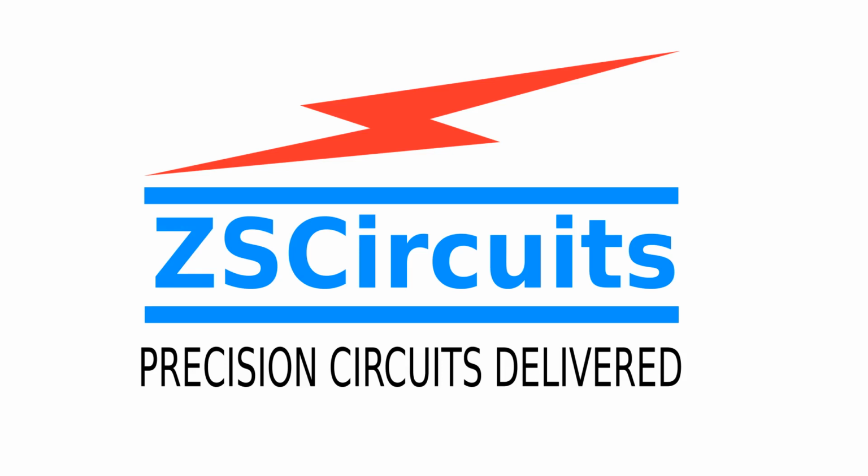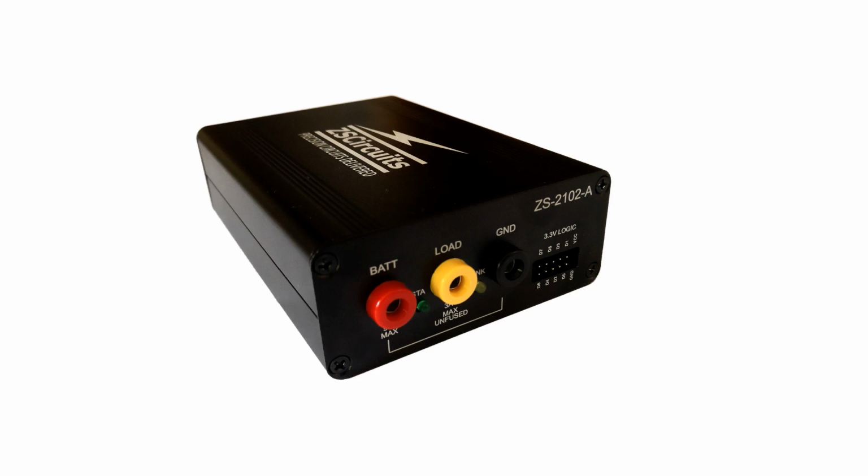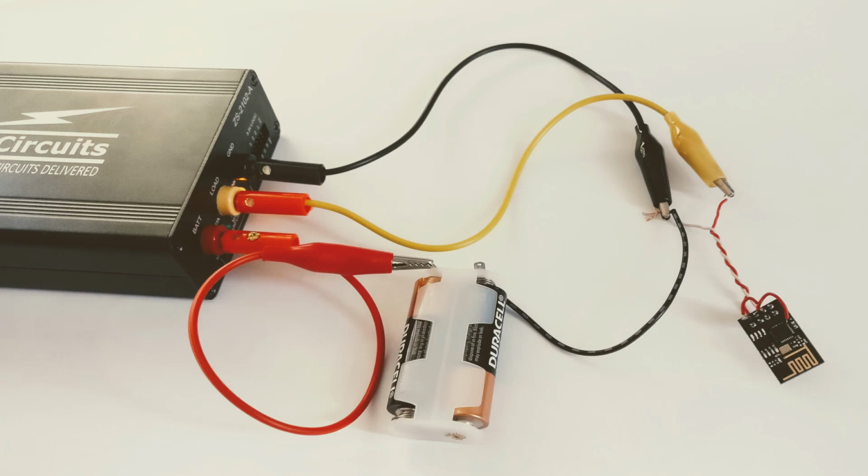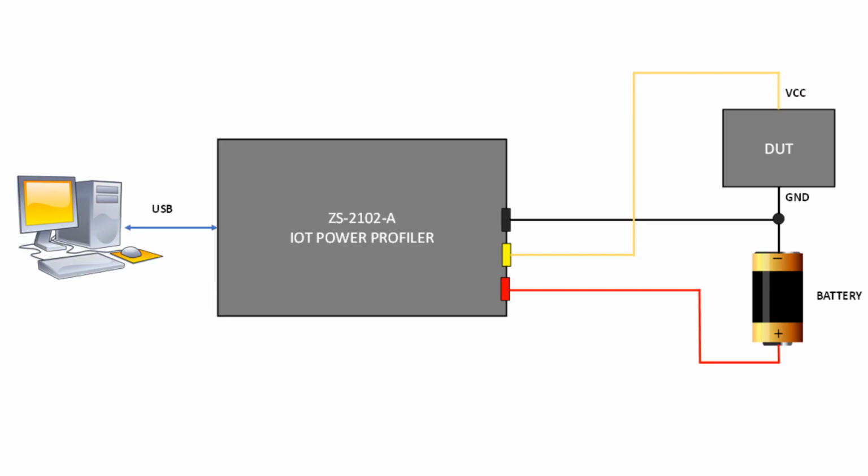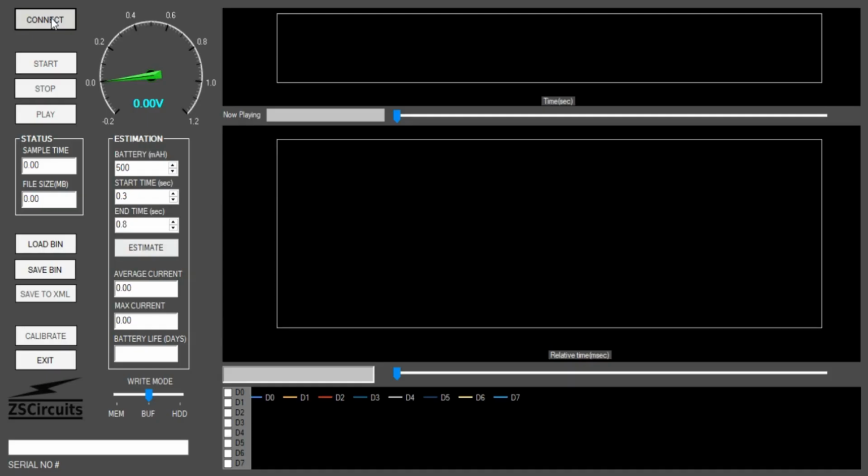This is a demonstration of the capabilities of the IoT Power Profiler tool, ZS-2102-A. In this demo, we measure the power profile of a popular Wi-Fi module, powered by two AA batteries. We connect the power profiler in series with the load, and to the PC using a USB cable. Then click on the Connect button.